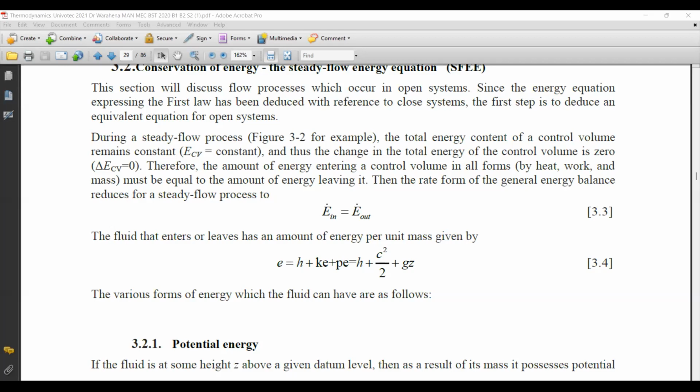So fluid flow stream can be considered as flow of fluid packets or parcels flowing in a sequence. And there is a flow pushing effect. Pushing means there is a force and the moving or displacement. So that is flow work of one parcel over the parcel next to it at the downstream.